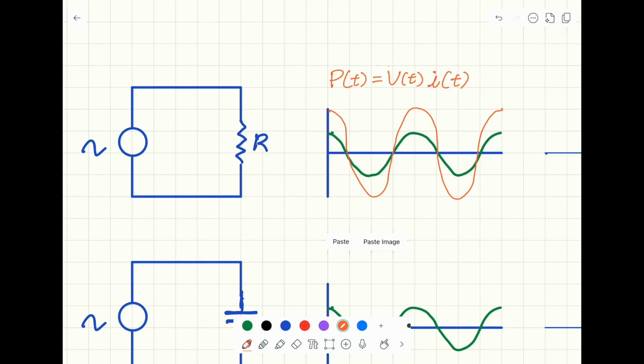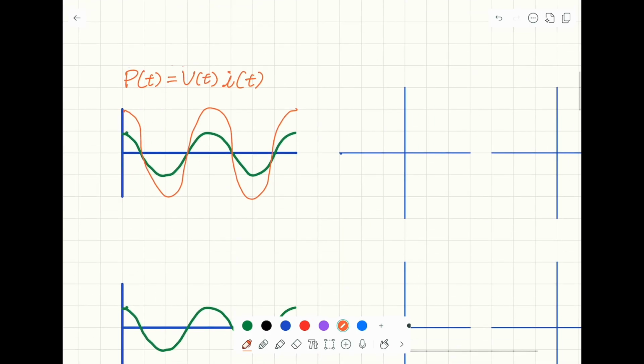The AC power is defined as the product of the AC voltage and AC current. In the case of a simple resistor, the power is non-zero, or positive, and this is the real power actually consumed or converted into heat or work in the load. And in the phasor, we'll put the current along here, and the voltage also in phase, so we put the voltage along here as well.